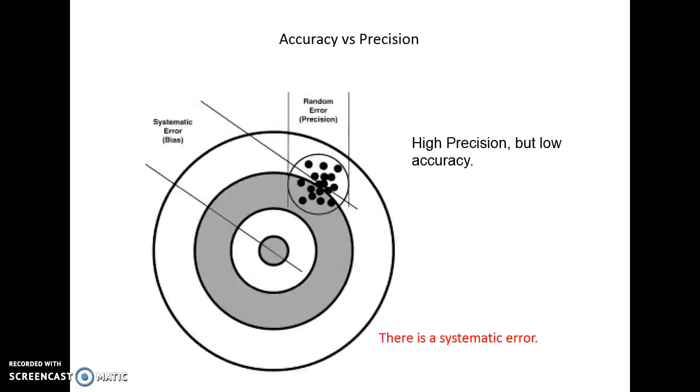And the next one is, what is the difference between accuracy versus precision? Precision means it should give the same value whenever measuring each time. So it may give the same wrong value whenever it is measuring. For example, instead of giving 15 voltage, it may give 11 voltage whenever it is measuring, but that is not accurate. Precise means all the values should be close together while measuring each time. An accurate value should be closest to the true value that you want to measure.